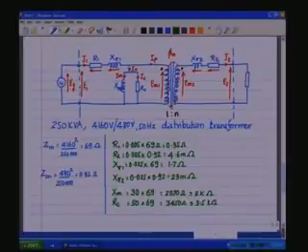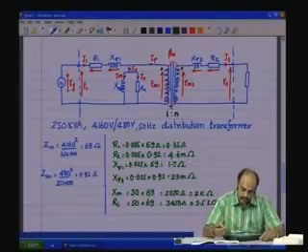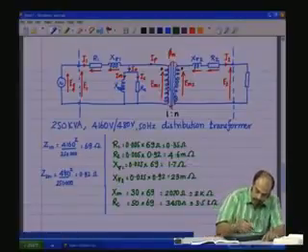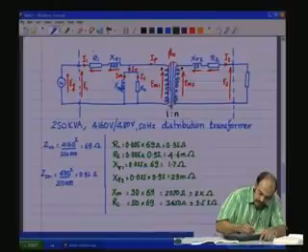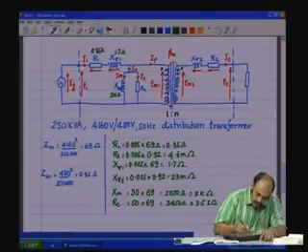Now this is the real impedance values, at least the order of magnitude or approximate values of the real impedance values of the transformer, which we can now write here. This is having a value of 0.35 ohms, this a value of 1.7 ohms. This is around 2 kilo ohms. This is around 3.5 kilo ohms.